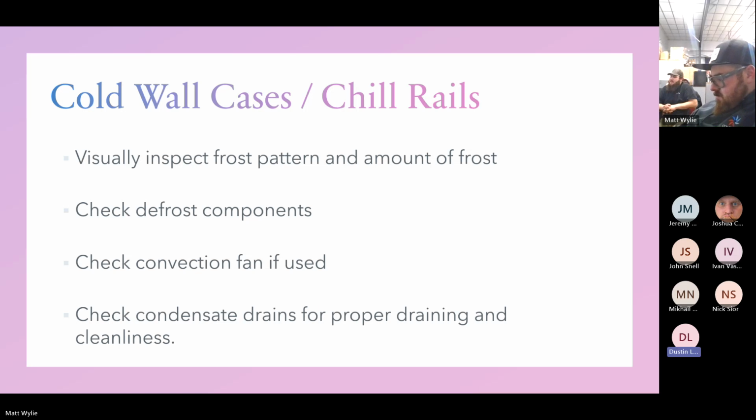Does anyone else besides me know what all the different filter dryers are? Like if you ever need to know a filter dryer, but the data tag on the old one is gone. Off the top of my head, let's do an 83, for example. You have a 53, an 83, a 33. The 80, the 50, the 30, if I recall, it's the volume of refrigerant they can carry, the cubic, whatever it is. And then the last number, the 3, the 4, the 2, is your line size. So a dryer ending in a 3 is a 3/8.